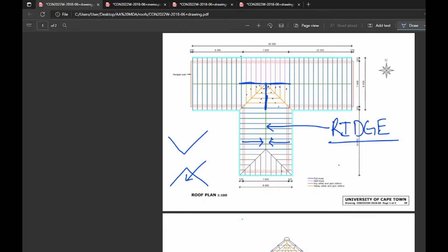and we start saying, how are these jack rafters supported? If you weren't aware of it, you would say, well, there's a green line there, it's fine. They are supported. That green line is nothing physical other than an apex, telling us the shape of the roof. There is nothing supporting them. You have to account for it, and you call it a ridge beam. Okay? And we're lucky enough to have a bit of a dimension there. We'll see how that calculation is done.